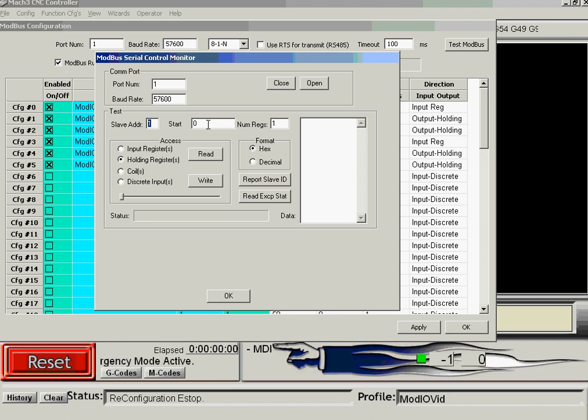Oh no, Modbus 2's got the MPG on it, so it would be more interesting to look at Modbus 2. And we're going to look at the data in register. So you refer to the manual, data in register appears at address 1151. So we start at 1151.